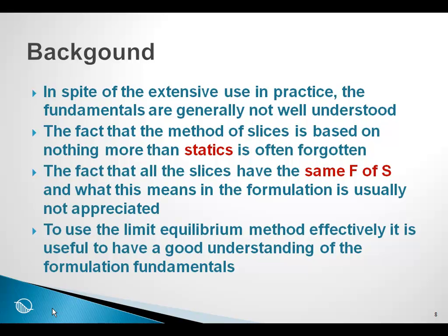Interestingly, in spite of the extensive use in practice, the fundamentals are generally not well understood. For example, the fact that the method of slices is based on nothing more than statics is often forgotten. Also, the fact that all of the slices have the same factor of safety, and what this means in the formulation, is usually not appreciated.